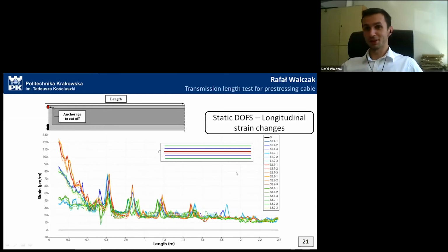Yeah, I think that it will not collapse suddenly, of course. Maybe due to fatigue, because it may be the case. I think it's an interesting topic for further research. But just losing the cable anchorage, I think, would not cause collapse in most cases. My idea in presenting this research in practice was to see if we could safely ensure the safe operation of such structures, because there are many of them in European countries, and the owners of such facilities are concerned about the technical conditions. So if we could show in the research that the failure of the anchorage would not lead to sudden failure of whole members or the whole structure, that means that they can be used.